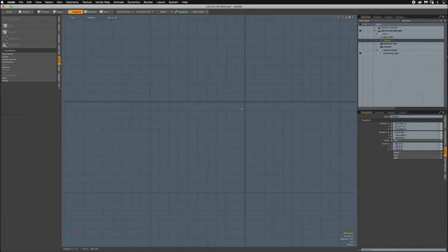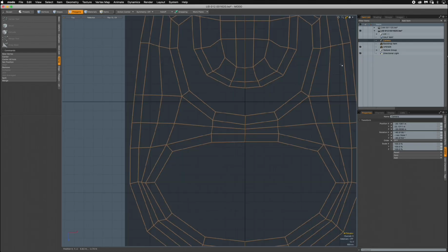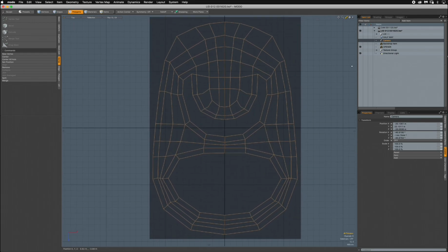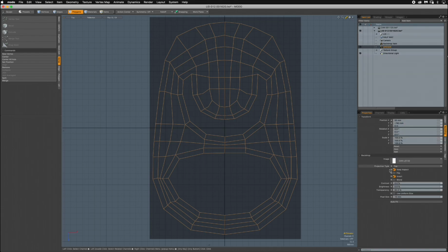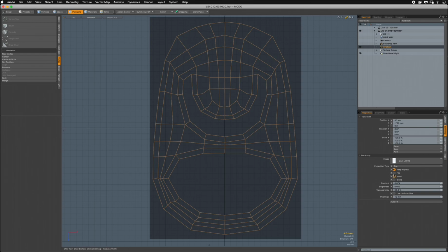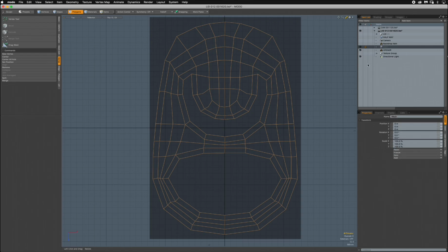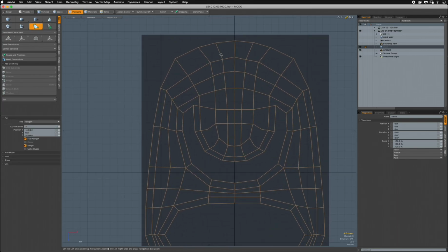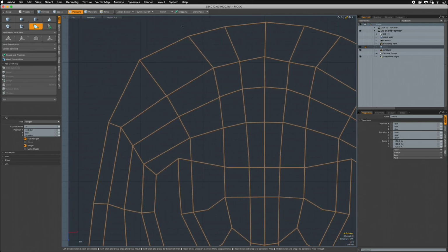Set the machine to top view, grab that image for the opener and place it on top. As you see, it's going to be pretty big. We bring it in and it will come in inverse, so I just invert the image so it's easier to work on. Then we start by clicking on a new mesh, so just DN, and then go back to basic, and then select this freeform poly modeling tool here, and we'll start by just building vertex 1, 2, 3, 4.